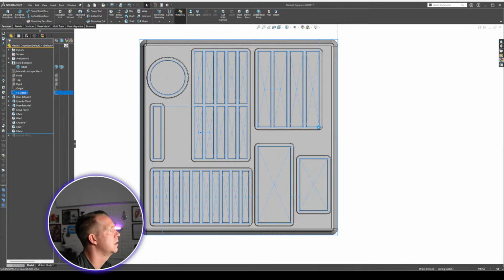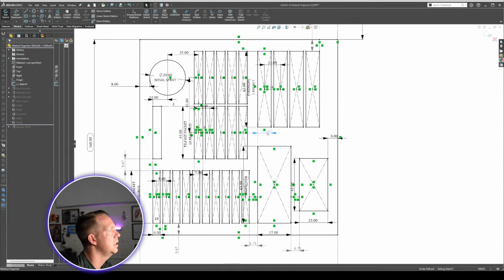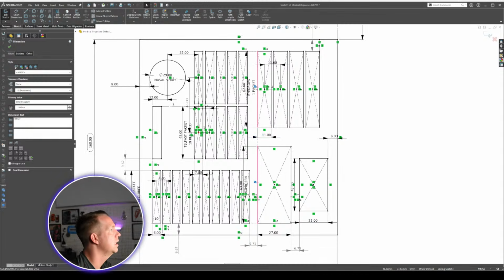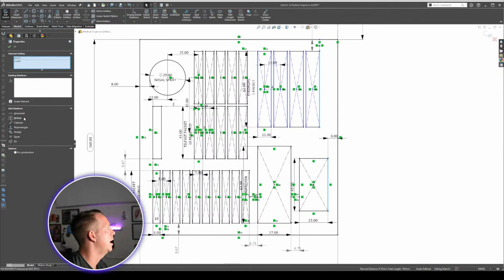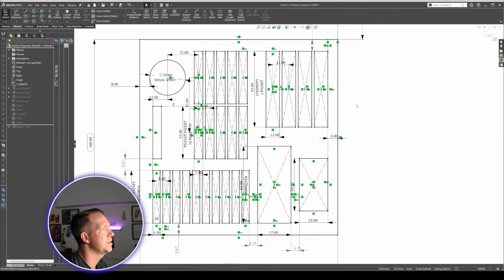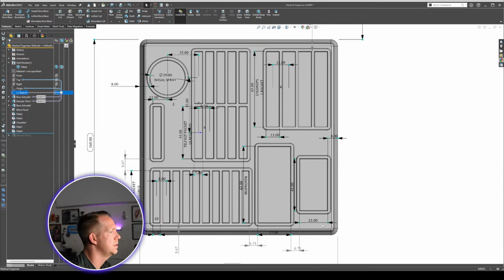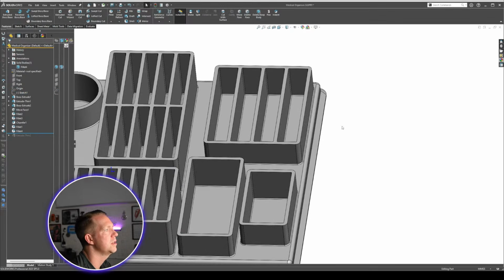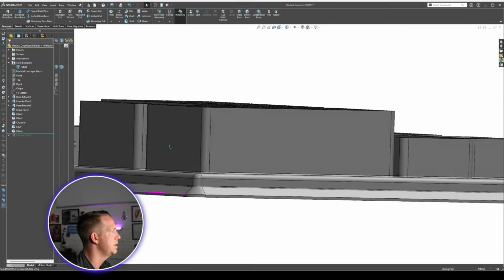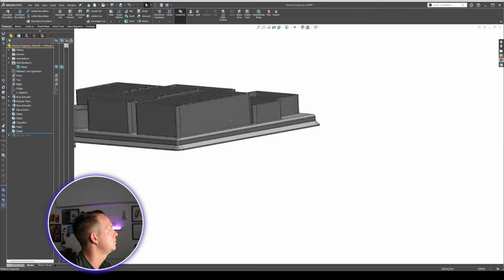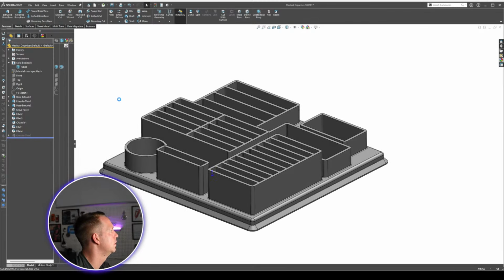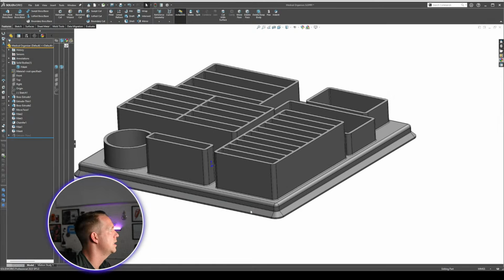And what I can tweak is I don't need these ones to be in line, collinear here. I'm going to grab this and make those ones collinear, so I'm moving those ones to the back. And then just tweaking those dimensions once again. So spacing's looking okay. Like on this side here, I don't have any weird fillets anymore. Everything's inside the front edge. So now it's looking much neater.